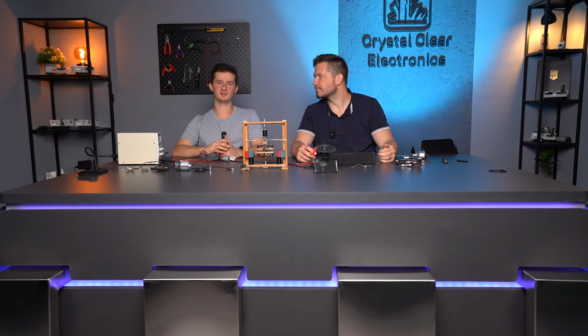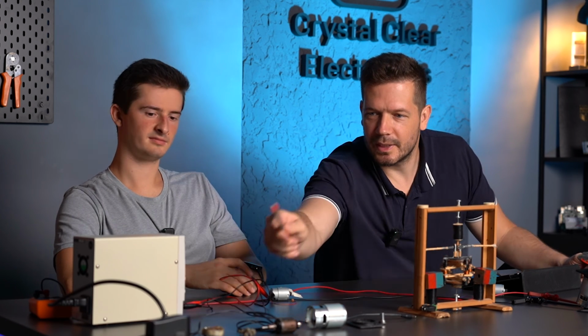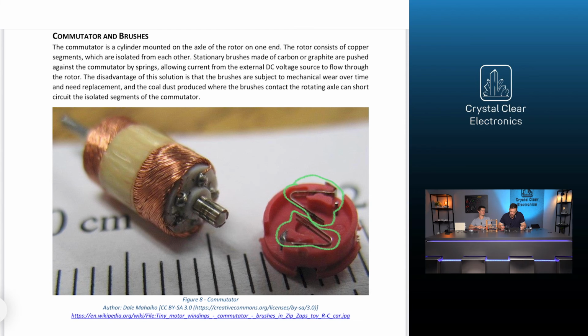And finally, a few words about the heart of the DC motor, the commutator, and the brushes that contact it. The commutator is a cylinder mounted on the axle of the rotor on one end. It consists of copper segments, which are isolated from each other. We will also take a closer look at this motor. Stationary brushes made of carbon or graphite are pushed against the commutator by springs, allowing current from the external DC voltage source to flow through the rotor.